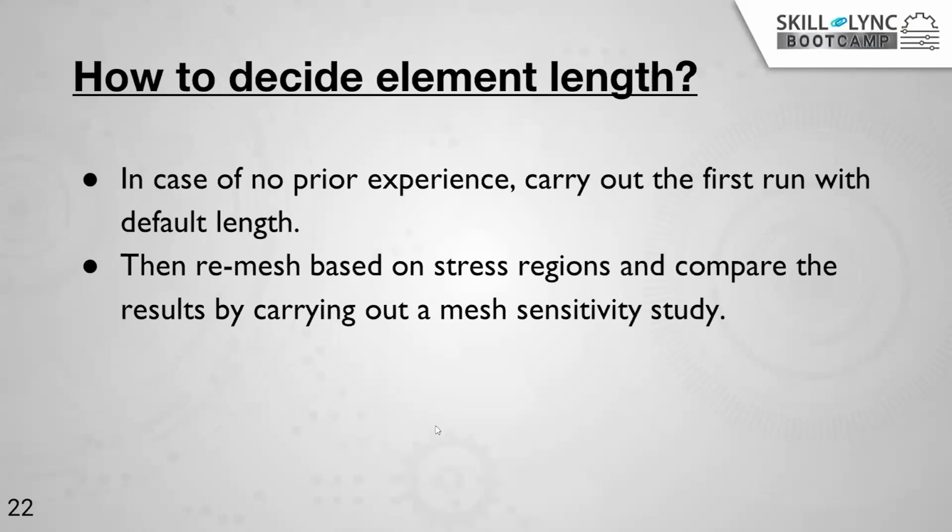In case of no prior experience of carrying out a similar analysis, what you can do is first carry out a run with the default length. You can just give a random mesh size based on your judgment and carry out the run. Then you would be getting some results, right? There might be regions of your interest. Then you can remesh those stress regions and compare the results by carrying out a mesh sensitivity study.